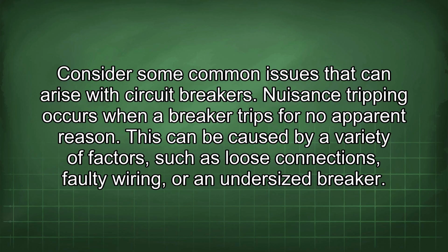Consider some common issues that can arise with circuit breakers. Nuisance tripping occurs when a breaker trips for no apparent reason. This can be caused by a variety of factors, such as loose connections, faulty wiring, or an undersized breaker.